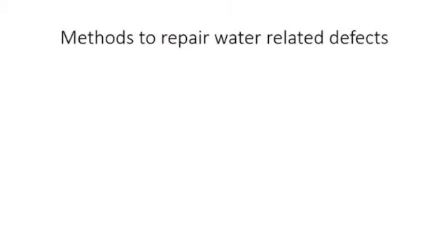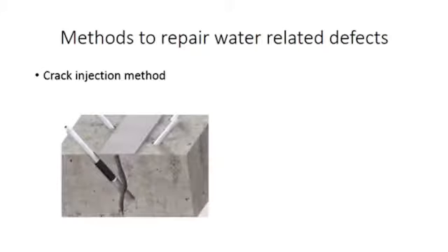There are two main methods used to block cracks in concrete, the first being the crack injection method. Different fluids could be injected using this method, although to stop water from leaking through these cracks, polyurethane foams need to be used. This foam expands almost 10 times its size when it reacts with water, and blocks any more water flowing through the crack.